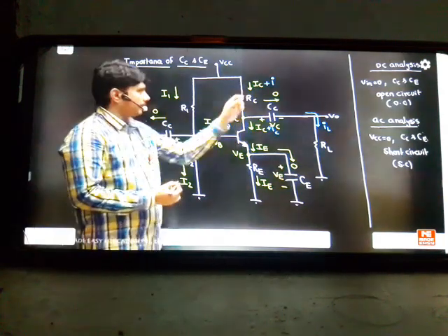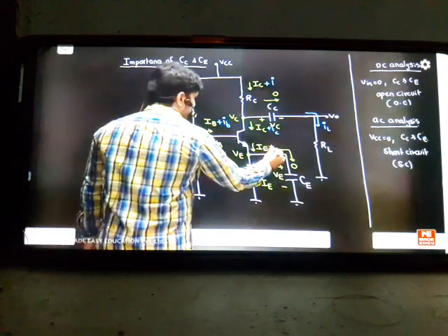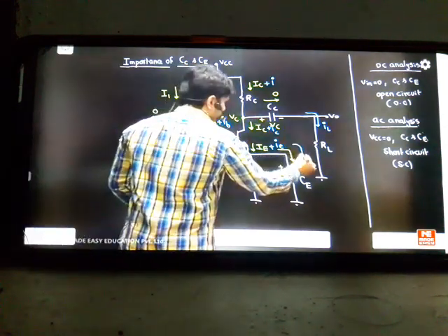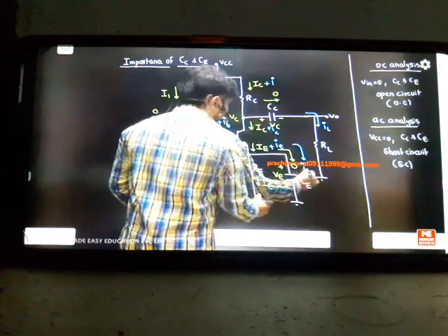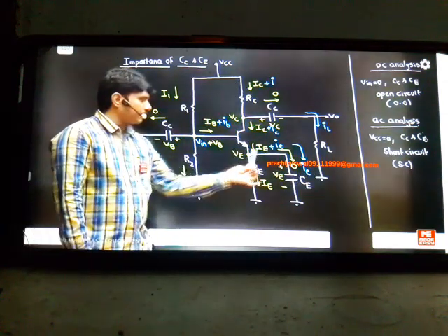The overall current will be I here. So you can see this is the technique happening. And this current, whatever you are seeing, IE plus your small ie will generate. But small ie can go to the capacitor because it's a short circuit. So this ie current will flow to C. If you observe, this small current is not going to capital R. It is just bypassing to this capacitor. That's why it is called bypass.